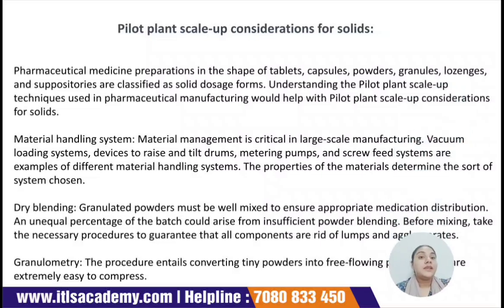So dry blending is again very important whenever you are dealing with any solid. You should always check whether the blending is done properly or not. Everything should be blended very properly, so as to avoid any lumps.